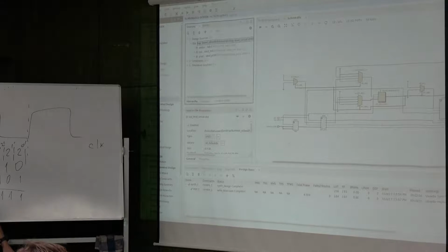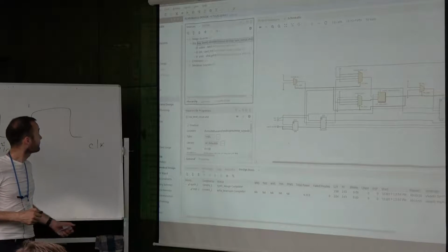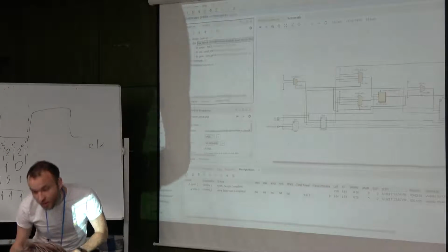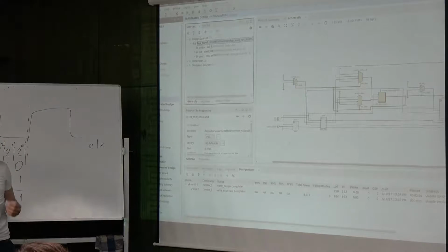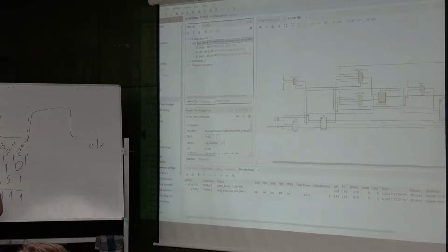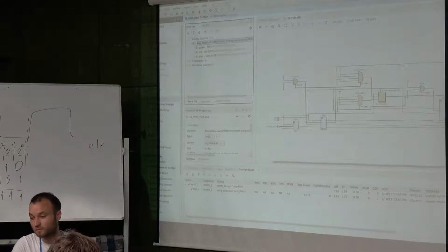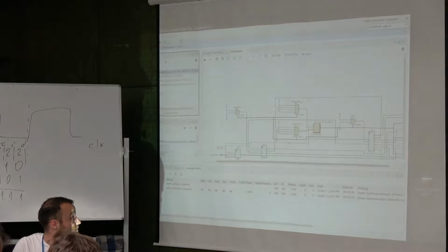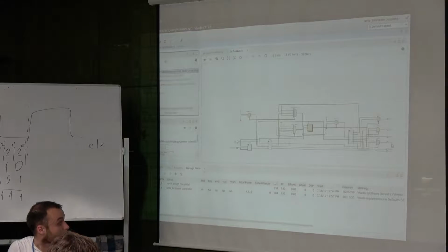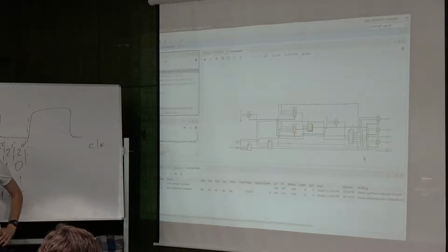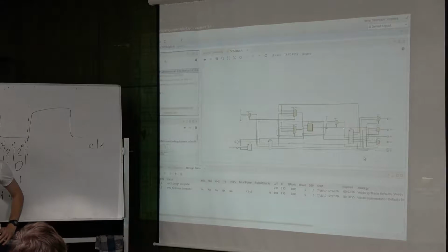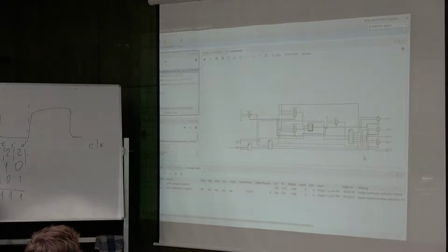Once you go through, you can't really see the navigation pane, so let me have a check. If you go to the RTL analysis tab on the navigation pane, you should be able to visualize your circuit using RTL, which stands for register transfer level representation. With the RTL representation, you can visualize your circuit, and here we can see three main subsystems. This is our adder, this is, I think, the printing circuit, and this is for initialization. And we have some wires to glue these circuits together. We can zoom in on the circuit of interest, which is this adder.